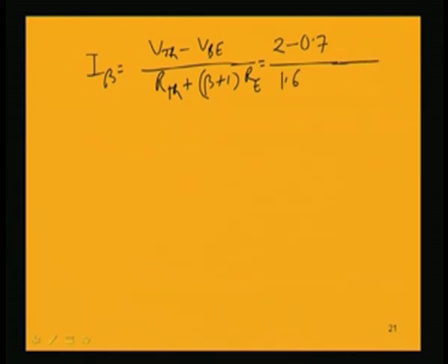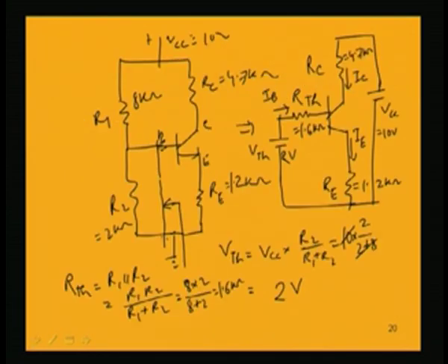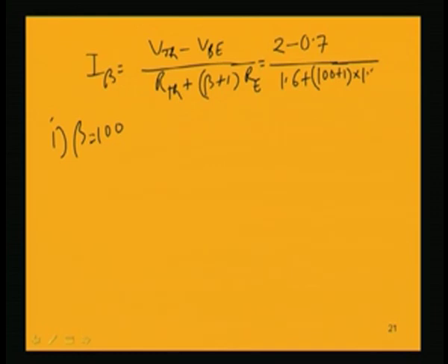I am keeping all this in K and this voltage is in volt. So, that finally the current expression will be coming in milliampere. So, 1.6 plus beta. Now, first case beta is 100. Let us take that 100 value, find out what is the current. RE is equal to 1.2 K, into 1.2 K. So, this value will be coming to be 0.01059 milliampere.